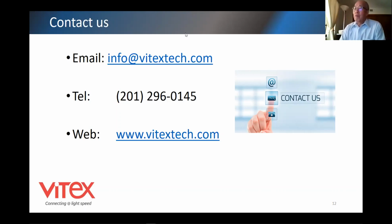If you are interested in CDLE, there is lots of material to cover this. There are different taps, different areas. Usually I don't want to go into this because this is done by the transceiver designer, right? So you don't try to tune it in a way that changes its characteristic. You just want to go through the MSA table, right?